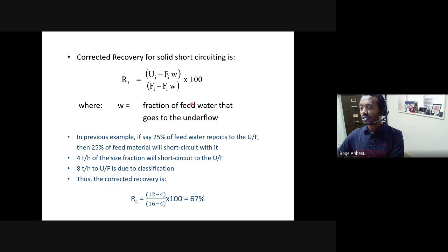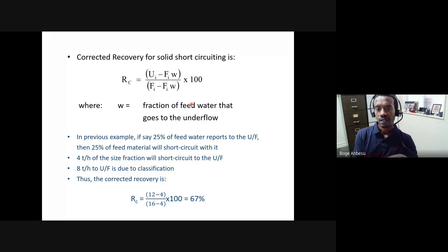But obviously, this is just for one size fraction, but we can do the same for various size fractions. So if I give you a feed, that feed doesn't necessarily have one size. It probably has a very wide size range. Okay, so you just mill something, for example, you just had a ball mill operating, producing particles that are very wide in size, from say 5 micron, 10, 20, 50 micron, 100 micron, 250 micron. So you have a spectrum of particle sizes produced as a result of grinding.